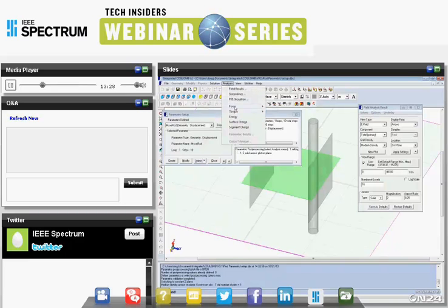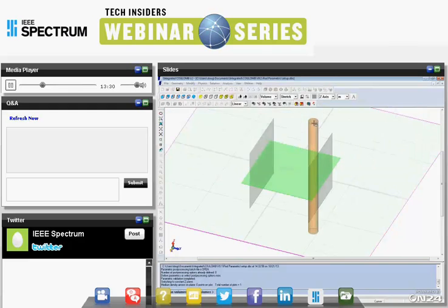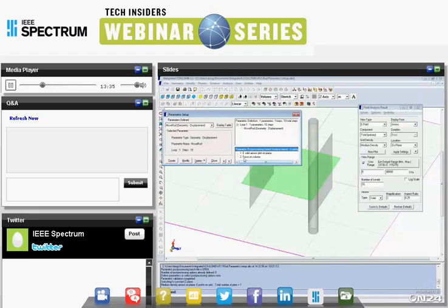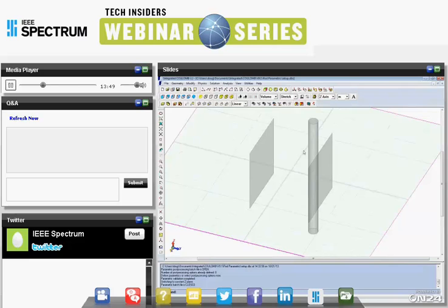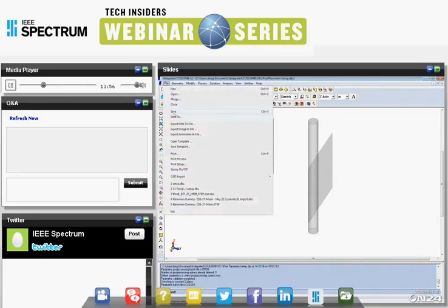Another obvious type of output for a lot of cases will be something like mechanical force. So you see now I've got my mechanical force on volume. Again, note the indication by the green coloring and the solid arrows on a plane. So we'll consider that sufficient for our purposes now. I'll close the dialogues and turn off the grid that's showing up. We'll save the setup file.